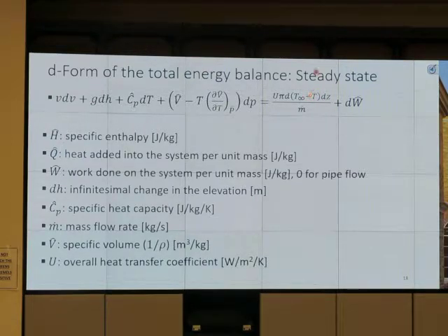When we lose heat, this term becomes negative, and it implies that the temperature has to drop. Yes? So, the work done on the system, is it positive? What is work done on the system? If I punch water, is that work done on the system? Kind of. If I turn on the pump, that's work done on the system. Work done on the system is positive in this definition.